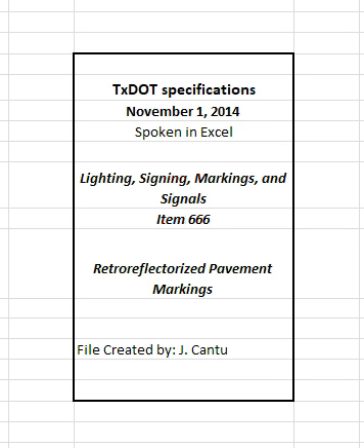3. Equipment. 3.1 General requirements. Use equipment that is maintained in satisfactory condition and meets or exceeds the requirements of the National Board of Fire Underwriters and the Texas Railroad Commission for this application. Apply beads by an automatic bead dispenser attached to the pavement marking equipment in such a manner that the beads are dispensed uniformly and almost instantly upon the marking as the marking is being applied to the road surface.